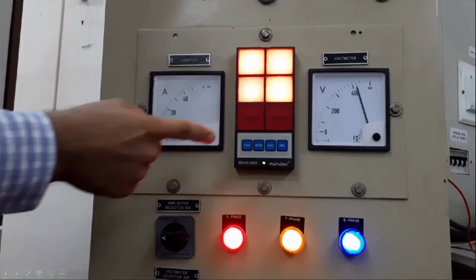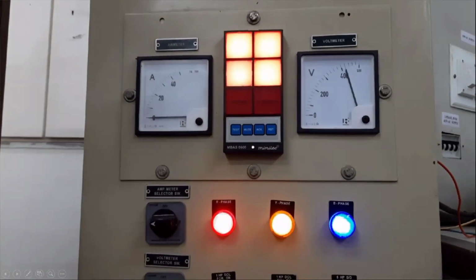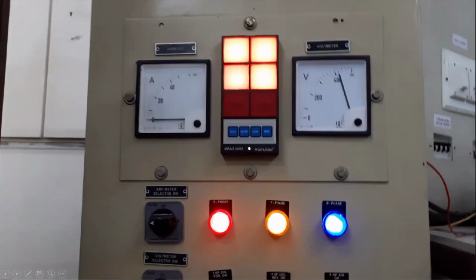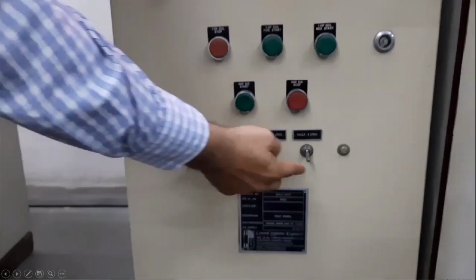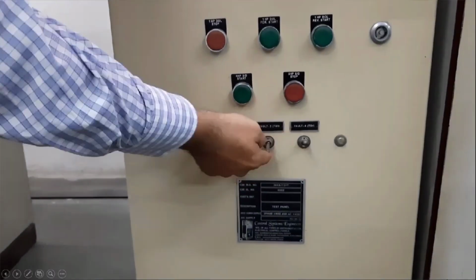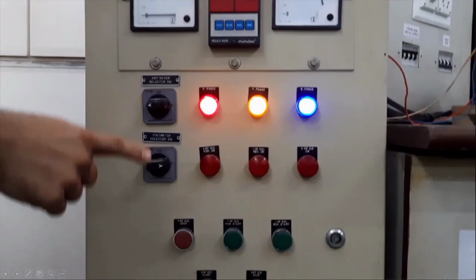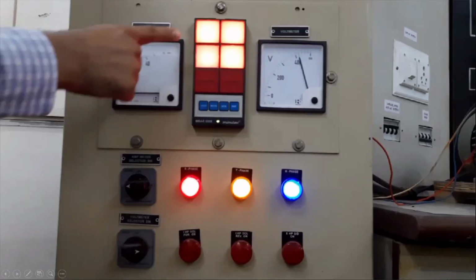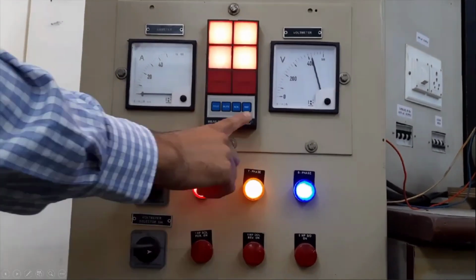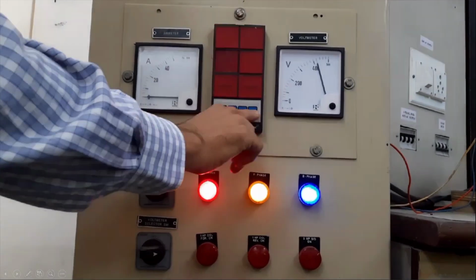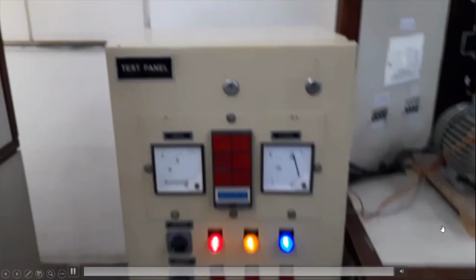Now I would like to reset, but as soon as I press the reset, it is not resetting. Why? Because the faults are still uncleared. So first of all, we have to clear the fault. So now I go to the toggle switches and I clear the fault. So 1, 2, 3 and 4. All four faults are cleared now, but still the annunciator windows are glowing. So now since all 4 faults are cleared, now I can press the reset button and now the fault is cleared. So this is the typical mechanism which is followed in industry in case of fault.